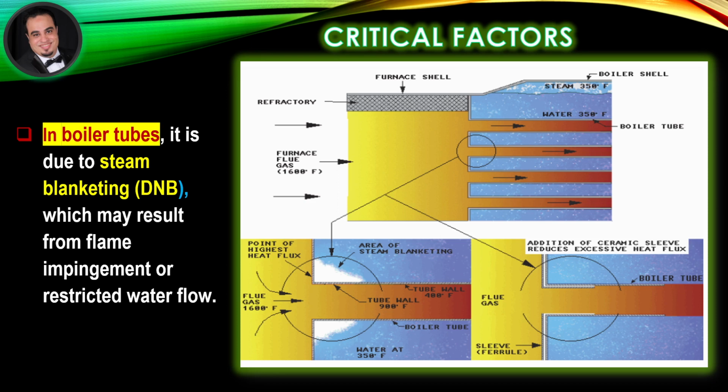When the heat flow balance is disturbed, individual bubbles join to form a steam blanket, a condition known as departure from nucleate boiling, DNB. Once a steam blanket forms, tube rupture can occur rapidly as a result of short-term overheating, usually within a few minutes.